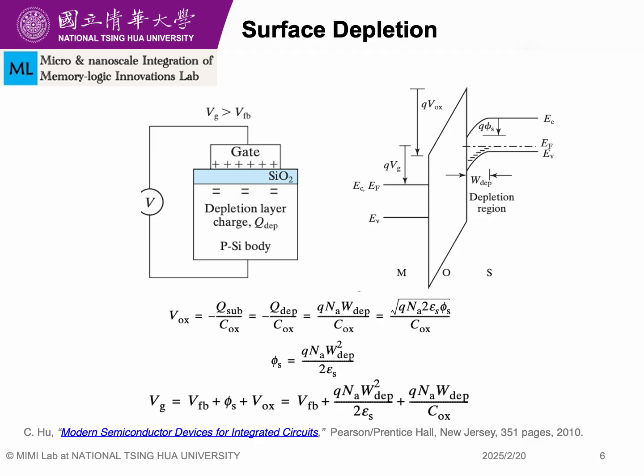Well, what previously we were discussing was, if we apply negative voltage in a MOS capacitor with p-type substrate, what will happen? As we saw, there is a condition called flat band voltage, and then a condition called surface accumulation, which is obtained when the negative voltage exceeds the flat band voltage. Now what will happen if we apply a more positive voltage, greater than the flat band voltage?